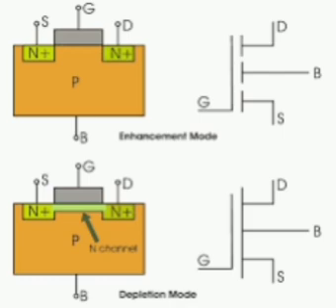Current gain of common base alpha is given by alpha equal to modulus of IC by IE, equal to beta by (beta plus 1), where beta is the current gain of the common emitter. Beta in terms of alpha is beta equal to alpha by (1 minus alpha). Current gain of common collector gamma is given by gamma equal to beta plus 1, equal to 1 by (1 minus alpha). Beta for DC analysis is greater than beta for AC analysis, that is beta DC greater than beta AC, or capital HFE greater than small hfe.